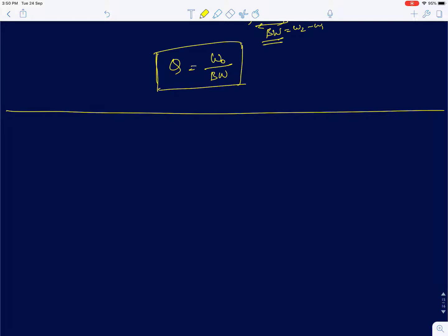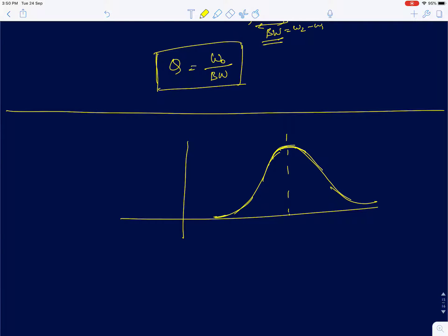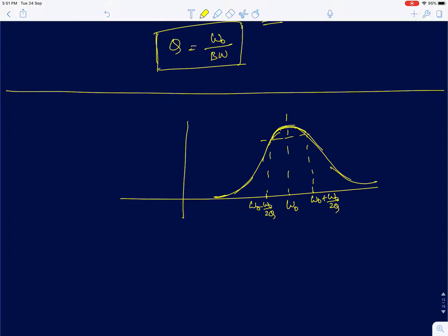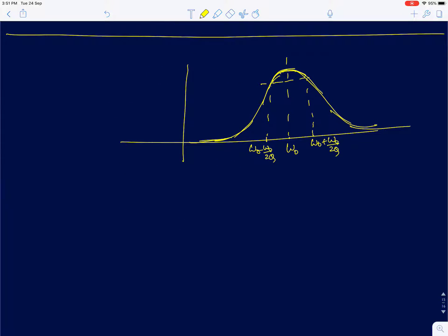comparing the bandpass RLC response to a low pass response. So if you look at the bandpass RLC response, we discussed RLC impedance, the frequency response of the RLC circuit, the impedance of that, it was actually something like this. You had the peak at the center, and we also defined two terms called the 3 dB frequencies, which are omega naught plus omega naught by 2Q and omega naught minus omega naught by 2Q. Both of them extend to infinity after that, and so on.